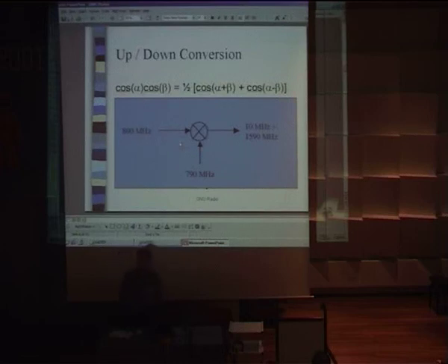Typically, they've got this thing called a double balance mixer, which is a non-linear device that pretty much has this math happening. There are solid-state versions with filtered cells. And they have a few non-ideal properties that you've got to worry about when you really start to build radios. But fundamentally, this is the piece that's happening.